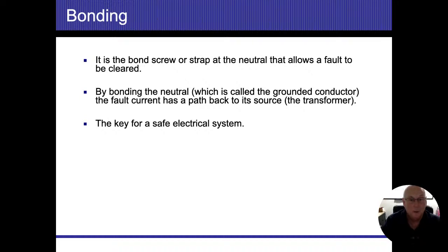All right. So when I identify it and I follow the conduit or I follow the GEC going wherever it goes, I want to make sure that it's not cut and I don't have 2 connections under a mechanical splice. I'm not allowed to do that. There is one type of splice that I could do. It's called a pressure splice. They'll put a hydraulic tool on 2 pieces of wire and squeeze the living daylights out of that thing until they meld it into one wire.